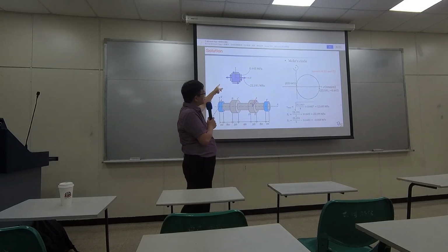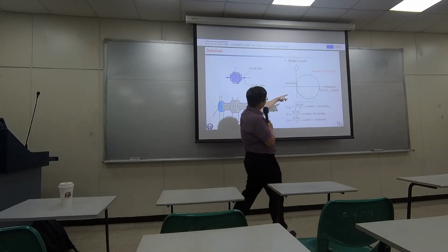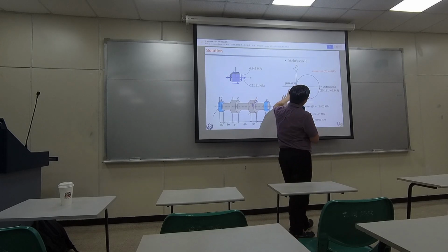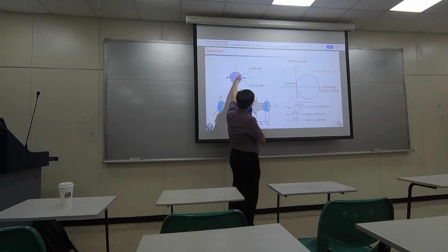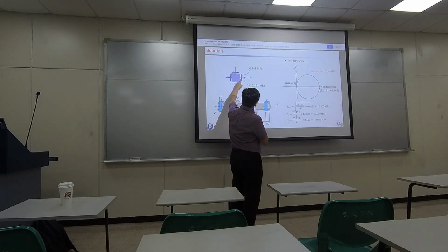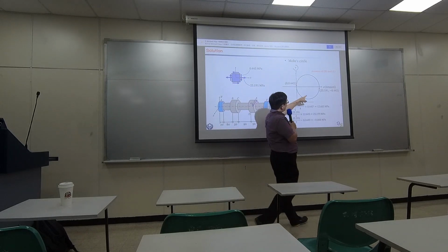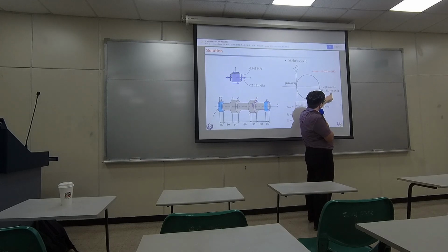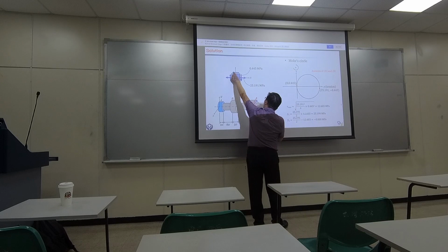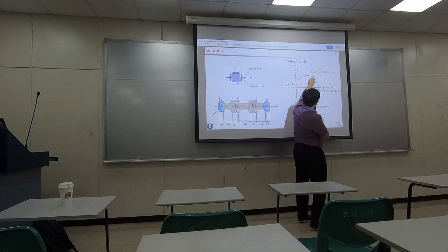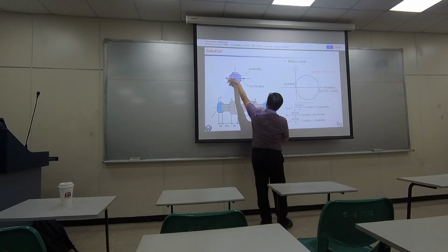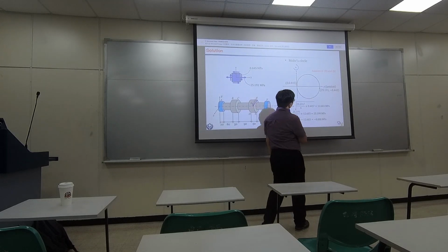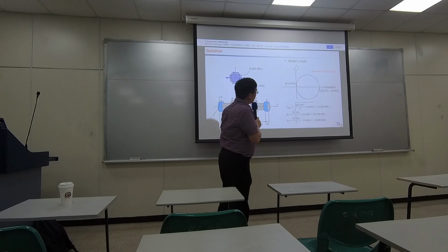If you want to draw a Mohr circle, it's going to be something like this, exactly like how I did it, but this time the shearing stress goes down on the right edge. So at the beginning, this is a negative value for point A. Rotate by 90 degrees, then I rotate 180 degrees. I have counterclockwise shear, so I have a positive value over there. So you draw the Mohr circle.